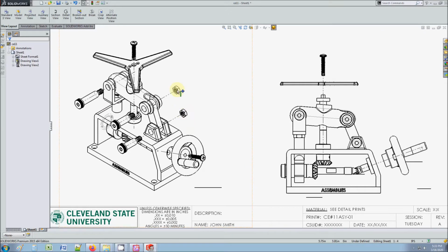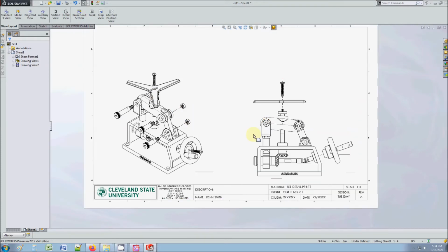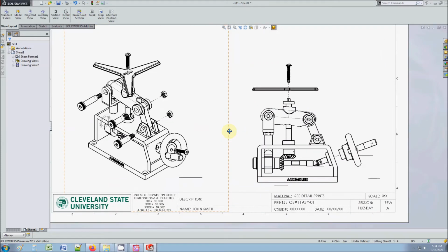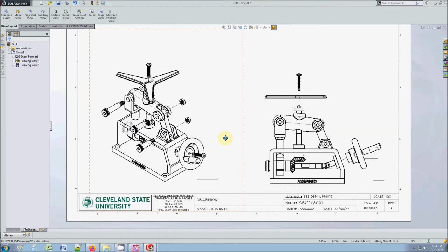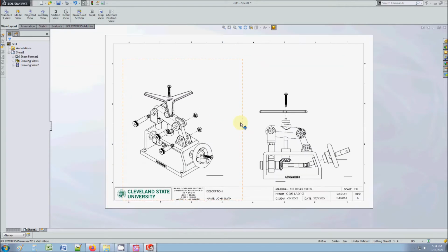Also, did you notice how this is the same nut for the assembly? That's really good practice. When you design, use the same hardware throughout your machine. Don't use crazy values everywhere, because that just makes it difficult. Even just for maintenance, let's say something broke in your house, you don't want to spend hours trying to find what kind of thread it was. Think of how nice it'd be if everything was the same. It's like, oh look, it fits perfectly. You didn't have to spend any time searching for it.